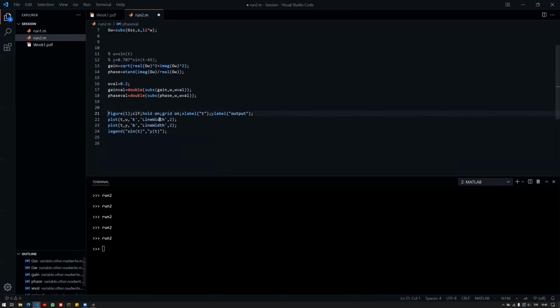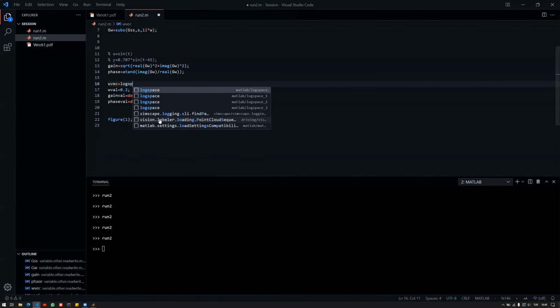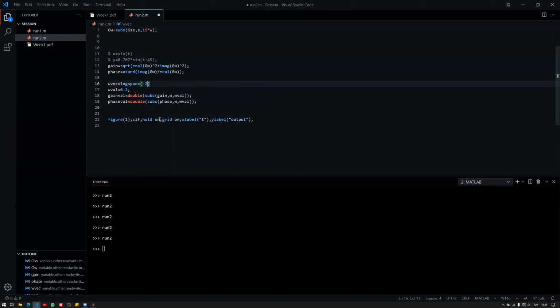Now, instead of calculating this stuff here, let's try to plot the Bode plot. For that, as was the case for the root locus, we need a vector for omega. Let's directly pick log space because we've already seen it. The reason why we will use logarithmic space in this case is that we will look at low frequency regions, mid frequency and high frequency regions in one plot. We want to combine them, and the log space is suited for this. If I have linear spacing, it will cost me some CPU performance, etc.